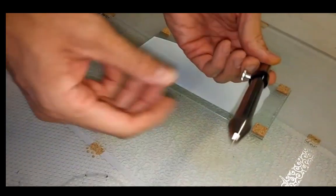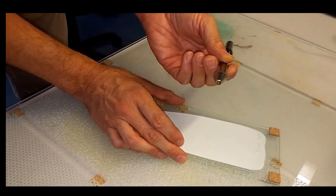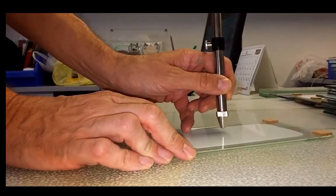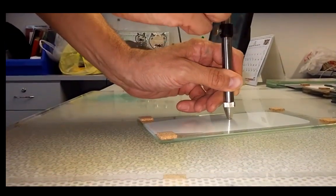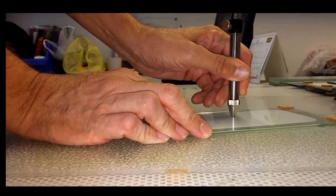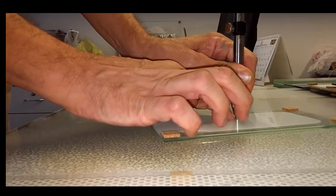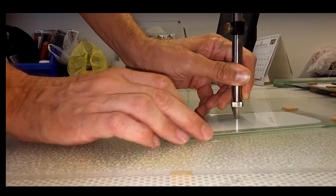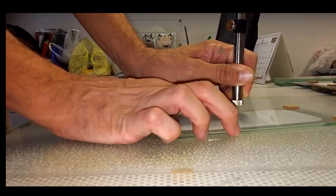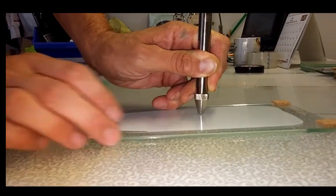Okay, now it's staying. In order to make the scratch resistance test, we hold it perpendicular to the glass and push down all the way until the tip goes slightly inside and the main part of the housing touches the glass. Then we release very slightly so that the housing is not touching the glass anymore, but we're still pushing down on the tip.